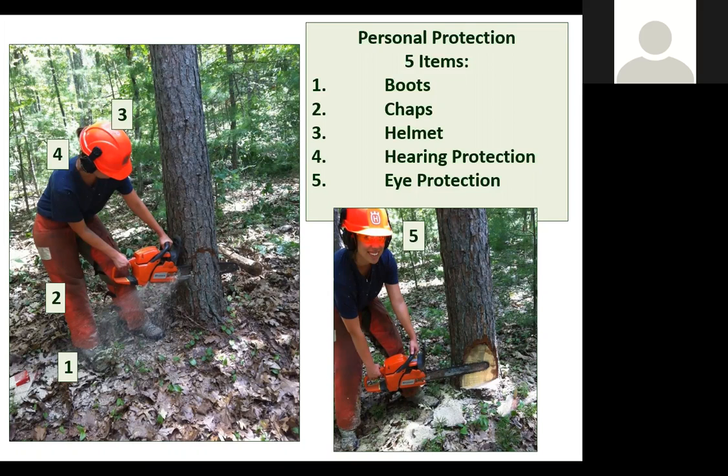Hearing protection helps me all the time keep from getting fatigued. It protects the ears certainly from damaging frequencies and loudness, but I also find that it's less fatiguing not to have a loud noise around. And then, of course, eye protection. You're going to be making chips. There's going to be flying debris, and either safety glasses or a helmet face mask, or both together, is something you want to make sure you have.